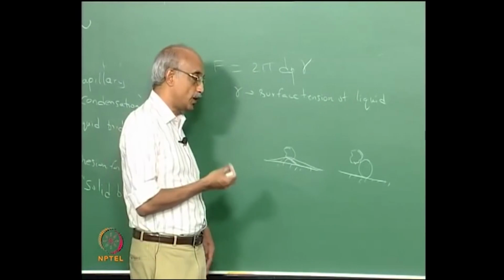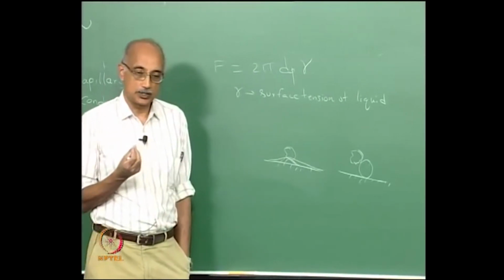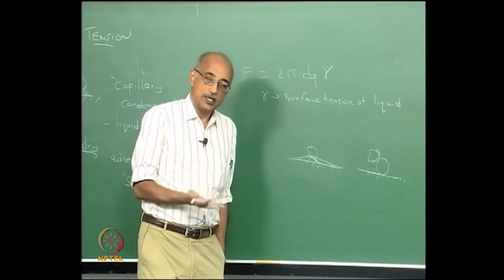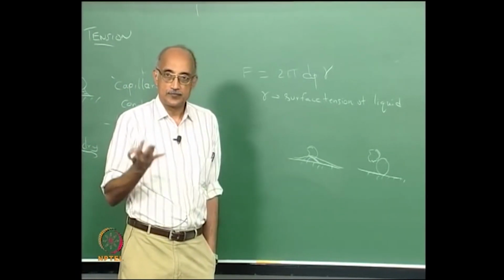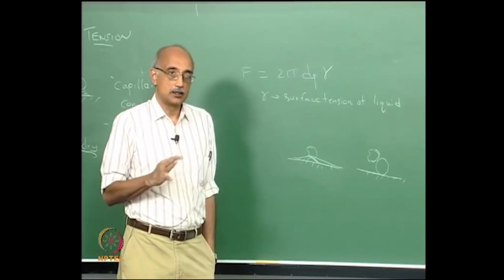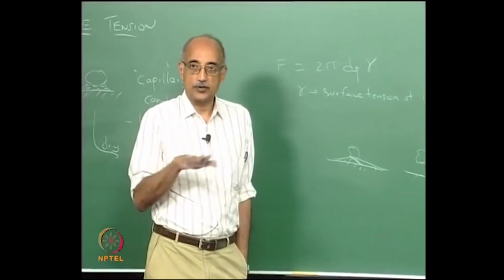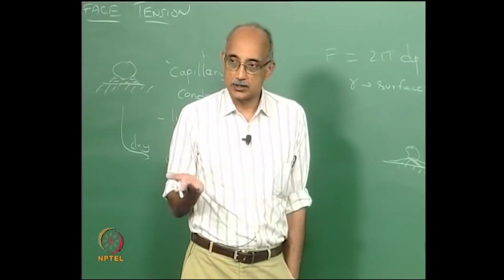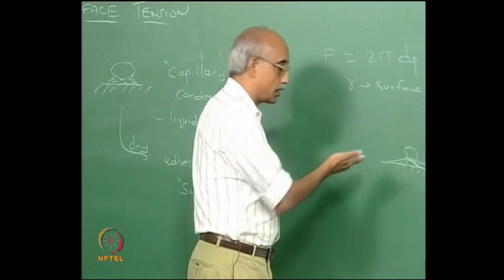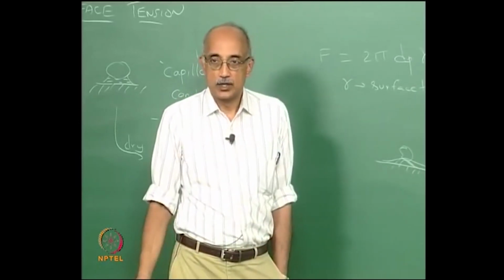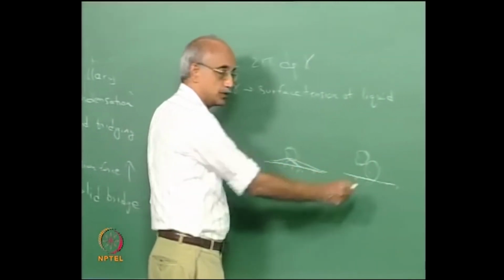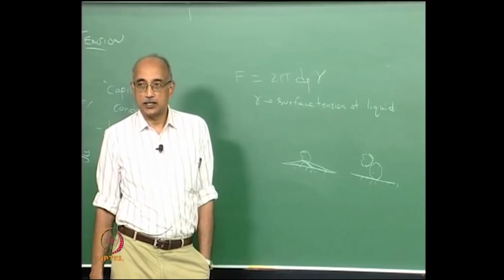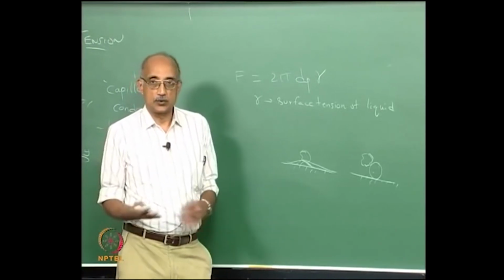So, it is a very important consideration that surface tension forces only come into play when the combination of the surface, the particle and the liquid is such that the liquid can wet the interface between the particle and the surface. So, if you have, for example, a hydrophobic surface and you have water as the liquid, it is not going to do this, it is going to do this. And so, surface tension forces are not going to come into play as something that increases adhesion forces.